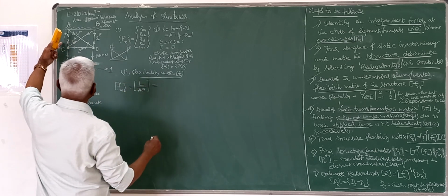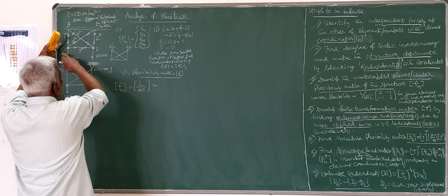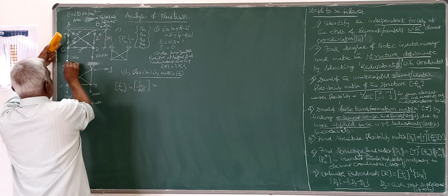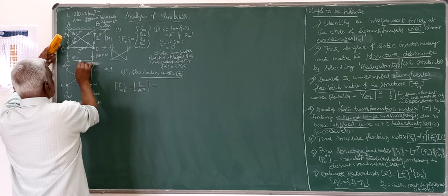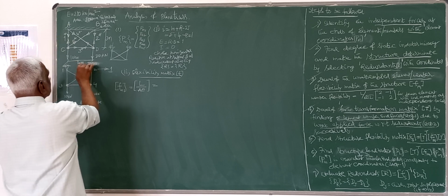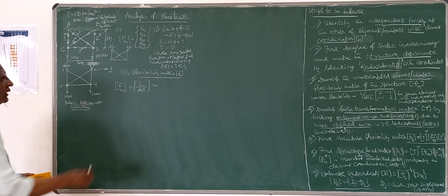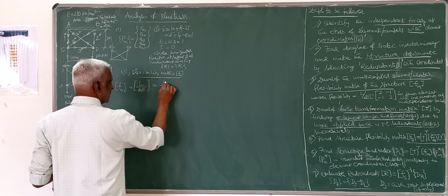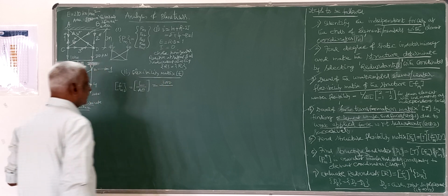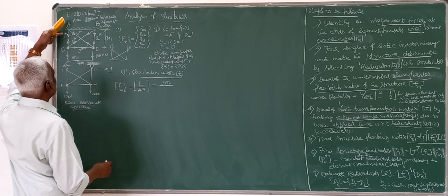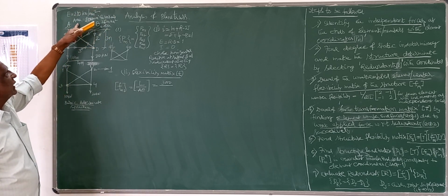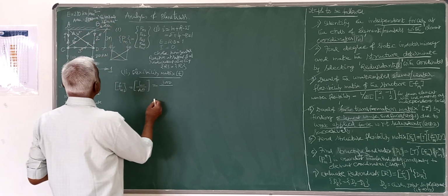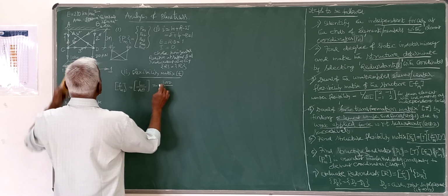For member 1, because it's a vertical member, you take height as 3 meters, length as 4 meters, so the dimensions you take as 3 meter, 4 meter. So for the first member, L is 3 meters, that is 3000 divided by AE. The A value for that first member is given here. Area of cross section is 2000 millimeters square for verticals and 600 for others.